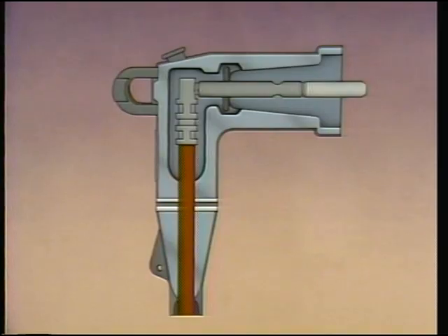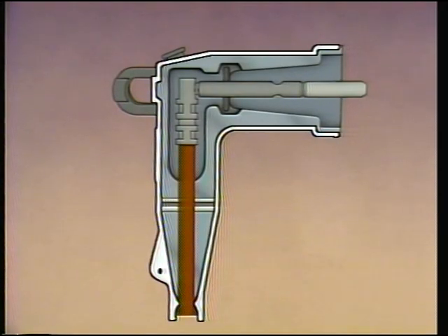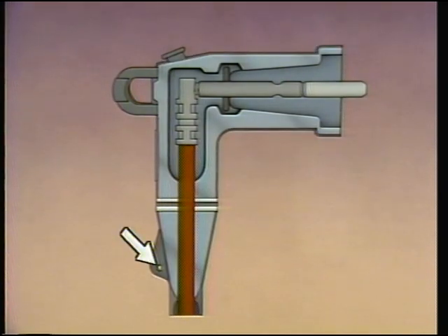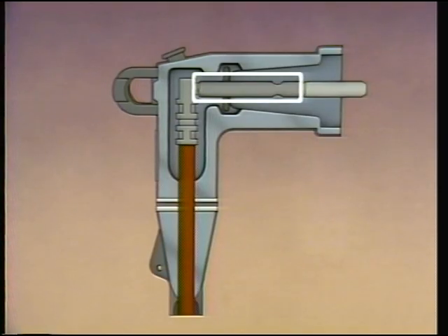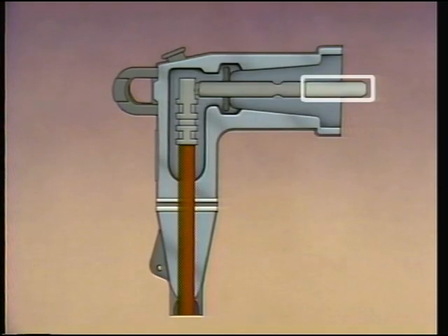To get an idea of how the two elbow terminations differ, let's look at an illustration of each, beginning with the load break elbow. This is a typical load break elbow. It consists of a connector, a conductive insert shield, a layer of insulation, a layer of semiconductive material, a grounding eye, a pulling eye, a male probe contact, and an arc extinguisher. Let's take a brief look at each of these parts.